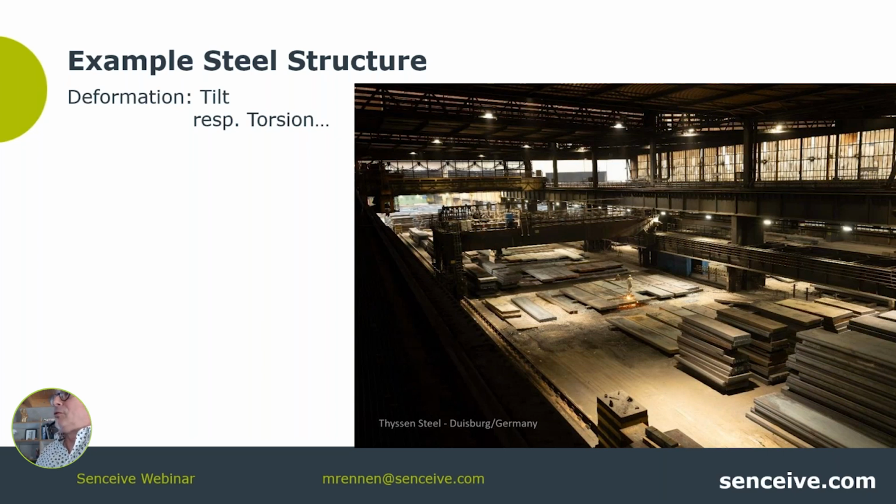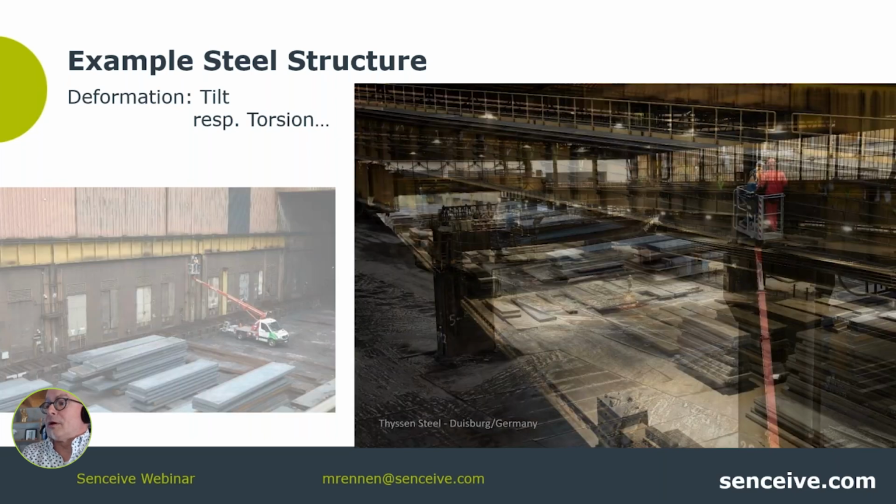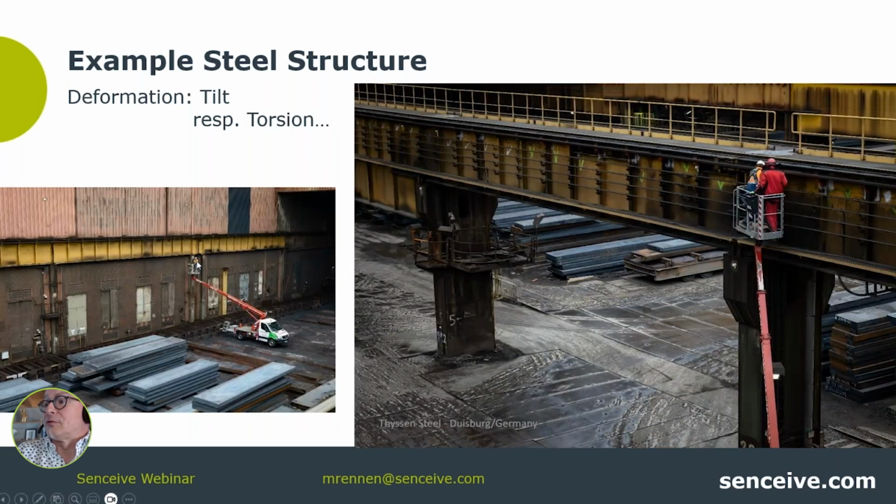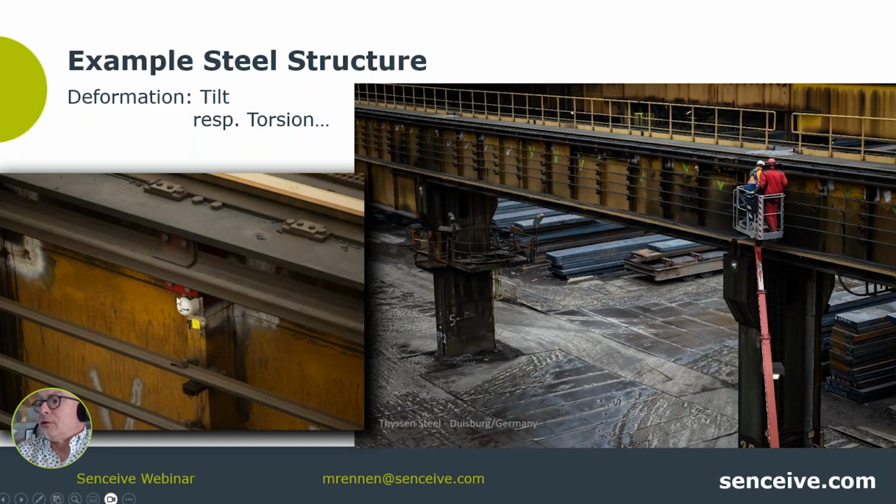This has been done in a geodetic way, leveling and total station observations, but obviously that cannot be done at a frequency that you can correlate it with the activity of the cranes. And that's why we were asked to install some sensor nodes there. See this here, this is one side beam where the crane is rolling on, and the other side is here, where tilt nodes have been installed at some crucial places where deformation is expected.